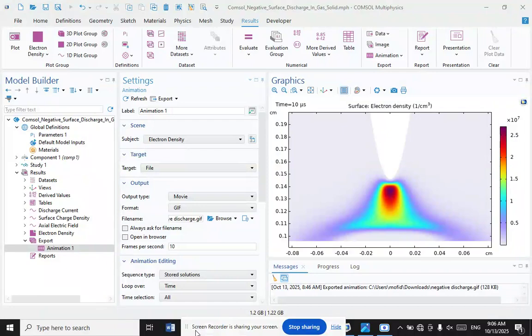In negative corona discharge, the electric wind is primarily generated by the movement of negative ions. Electrons near the sharp electrodes are accelerated, causing ionization and the formation of negative ions by attachment. These ions are repelled by the negatively charged electrode and accelerated towards the positively charged electrodes.